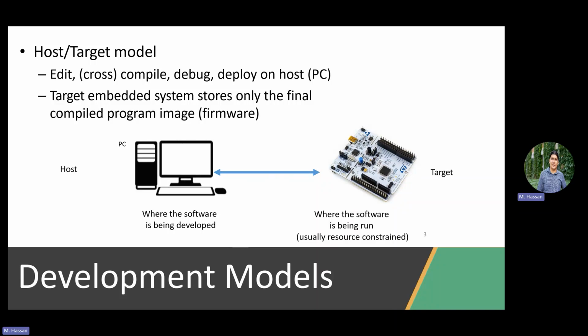So you need something that you can play around with, try different things, simulate, target different embedded platforms. And then once you are done testing and development, you just go and burn it there, right? So we call this the host-target model for programming, right? You are using the host for development that is different than your eventual target.